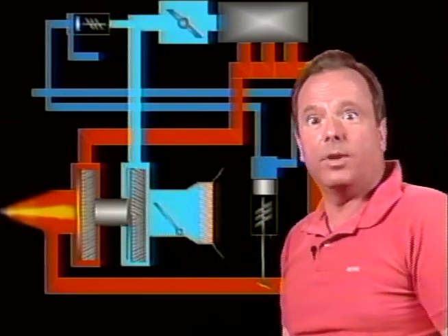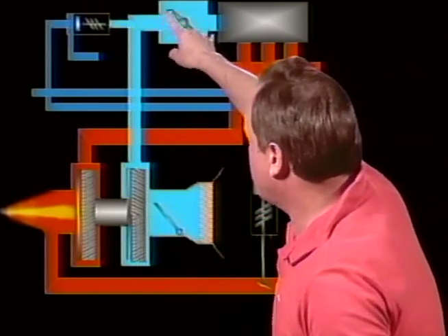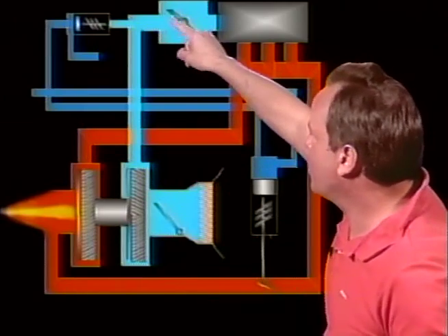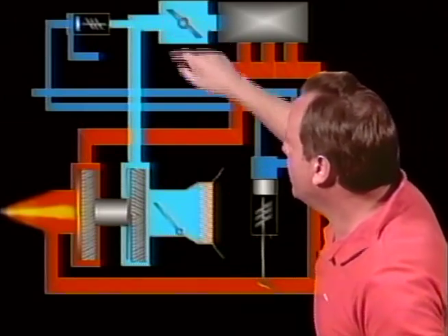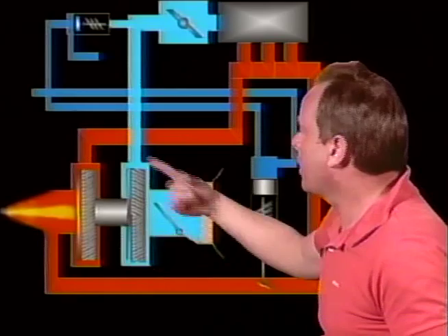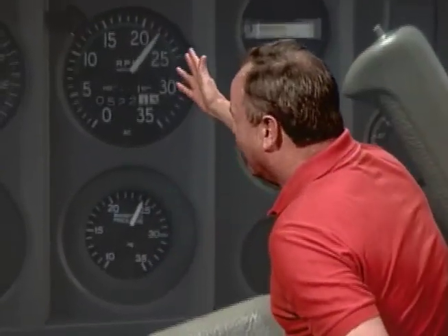So now let's take a look at what is the purpose of the differential controller. Well, the differential controller does something different, and that's the one that measures the pressure on each side of the throttle valve, and what it does, it functions during all positions of the wastegate valve other than the fully open position. It's constantly working except when you're fully open and then the wastegate closes and then you're driving the turbocharger as hard as you can. Now here is something that can happen in a turbocharged airplane that's considered to be a bad thing.